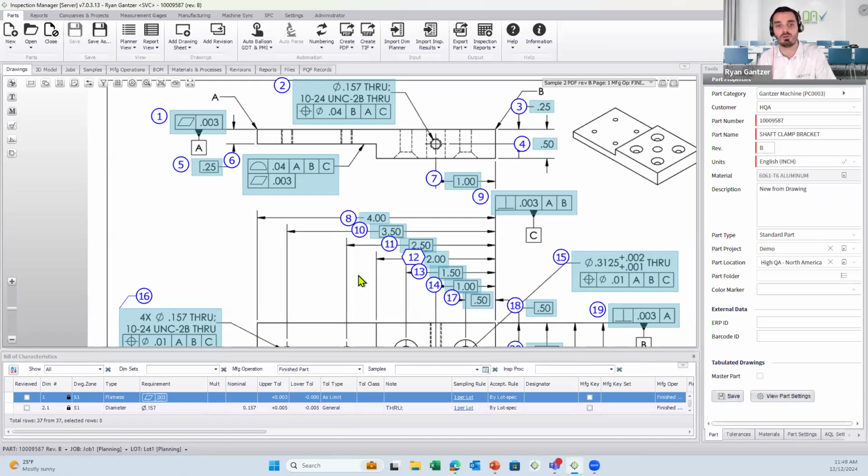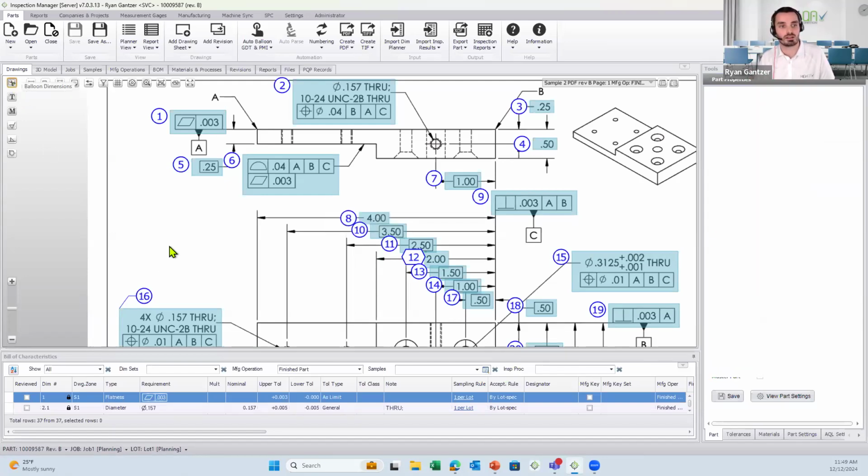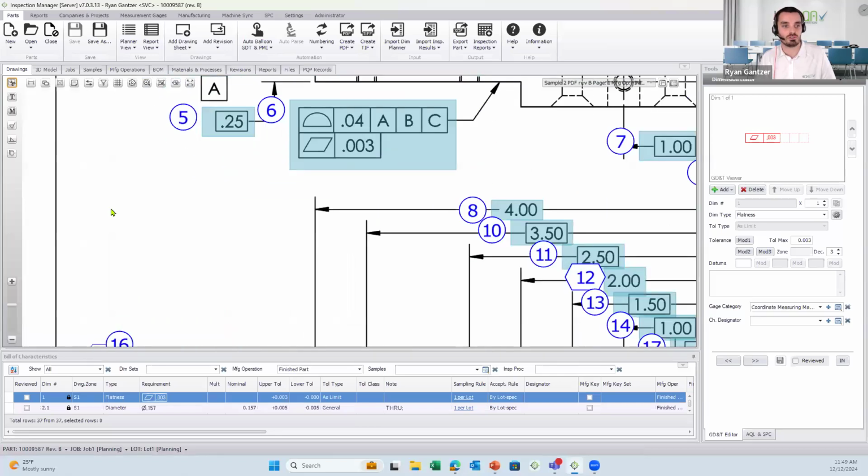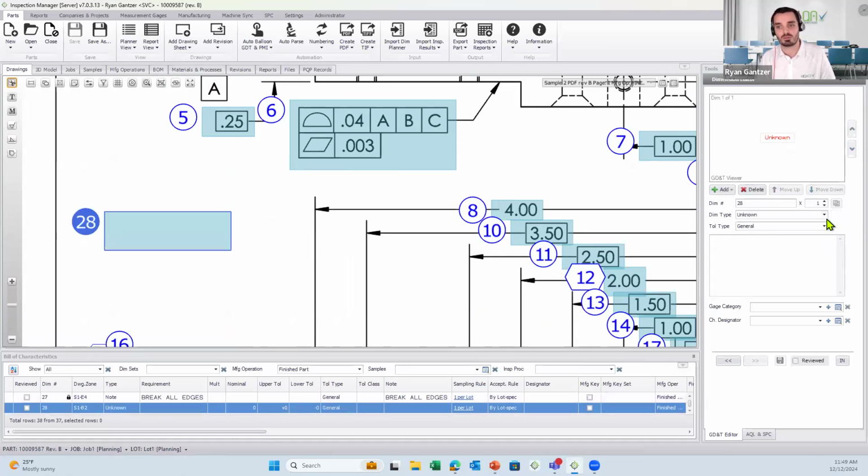But that's why we have those manual capabilities as well, where let's just click this scissors icon, pretend there was a hand-drawn dimension right here. You would just box select it. You can see what the system comes up with, but then always edit, right? It's a thread. And that's when you're just manually typing in that information. But once you do it once, it resides in the database. So if it's like a legacy part, for example, you have that part record completed, you only do that one time, then you just run multiple jobs up against that part record.